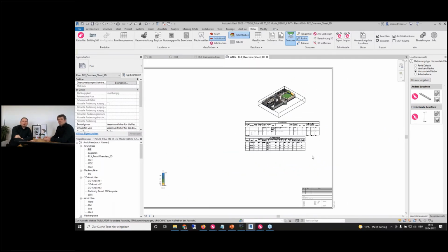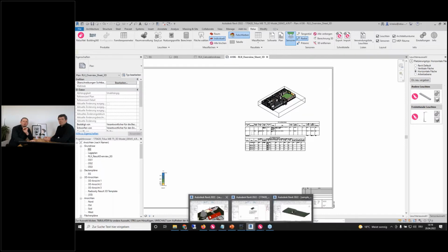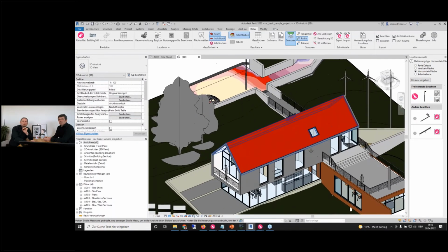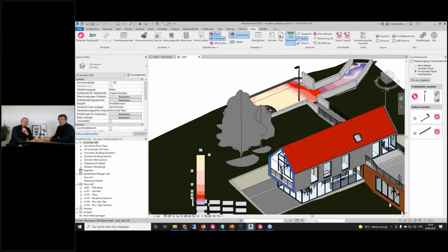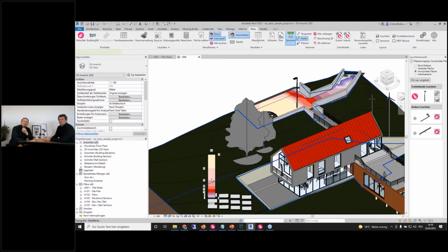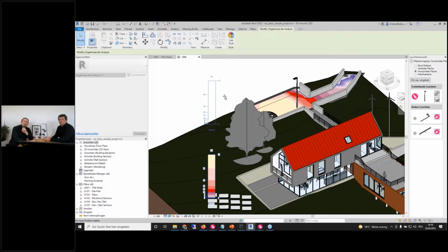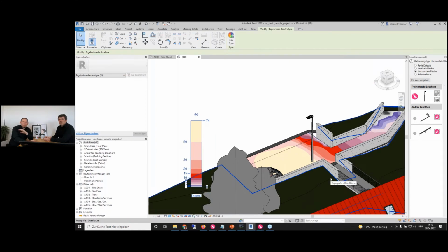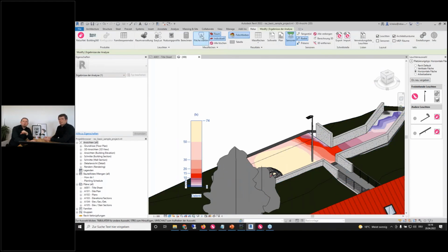So that's the indoor, and this picking area works also quite well in outdoor. So this is something we have prepared in this project here. This is a Revit sample with an outdoor area, and the same, no, sorry, too many clicks. The same stuff works in outdoor as well as in indoor. You have to pick an area, then do a calculation with the pocket calculator here, and then you get false colors, values, the tables, everything we want to have in photometric calculations for this area.